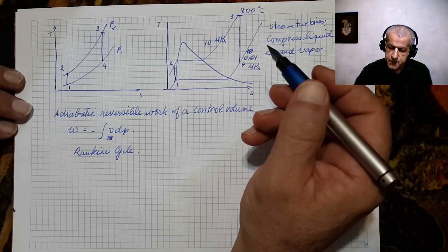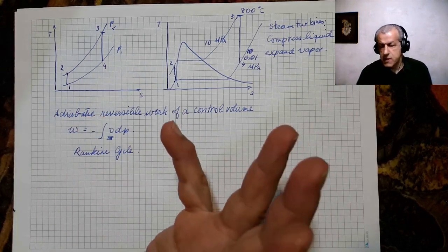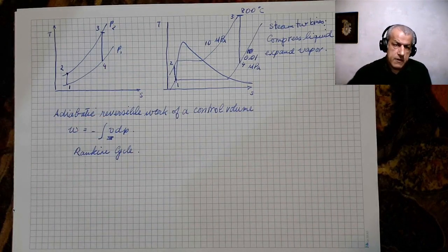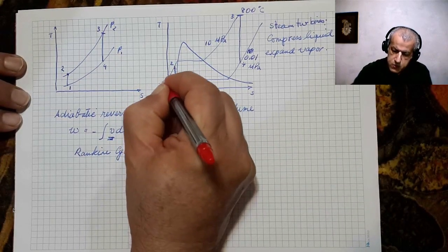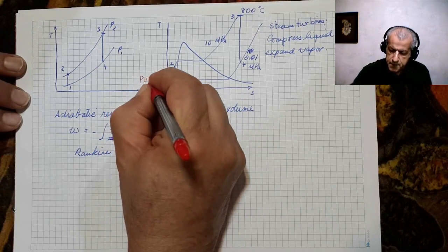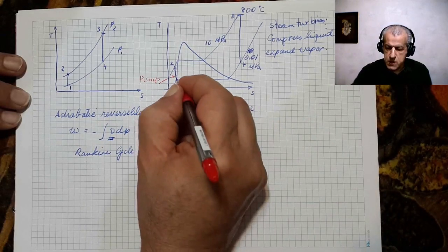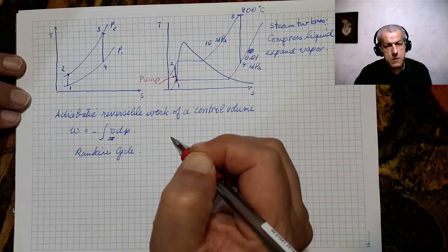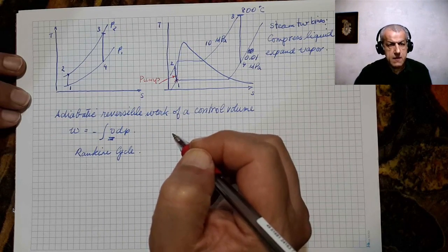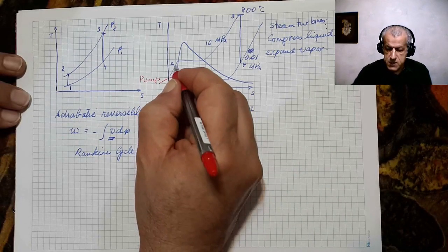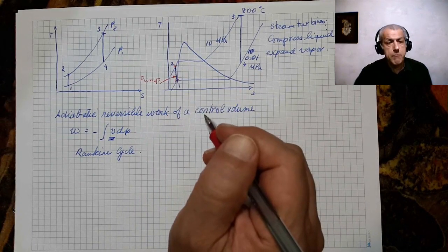You see, the different instruments that bring about this cycle are four. The basics are four. This work is done in a pump. So saturated liquid water at point 1 is taken and compressed to a higher pressure, to pressure at point 2, in a pump.